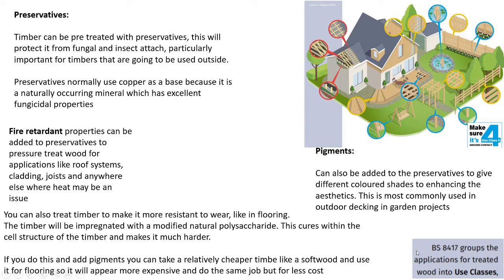Down here as well, I mentioned BS8417. This is to do with the treatment of timbers. BS stands for British Standards, and how British Standards work is it's always BS and then four digits. There are God knows how many British standards, and you'll come across them in loads of different things. I just wanted to put that in there so you can understand. Treatments of timber come under British Standard 8417. You don't need to remember that exact number, but understand what British Standards are.